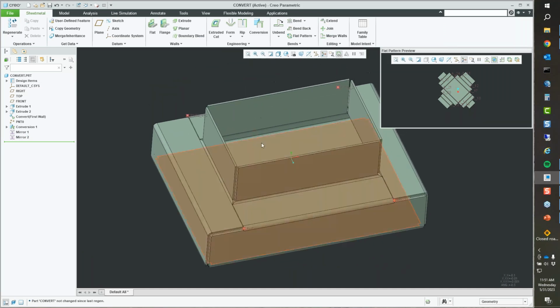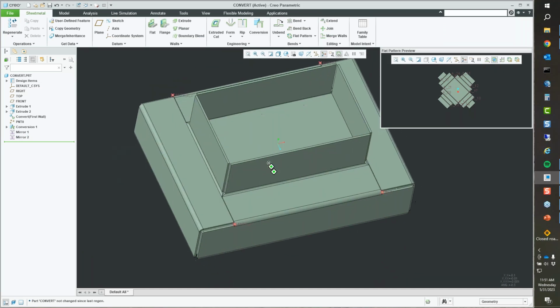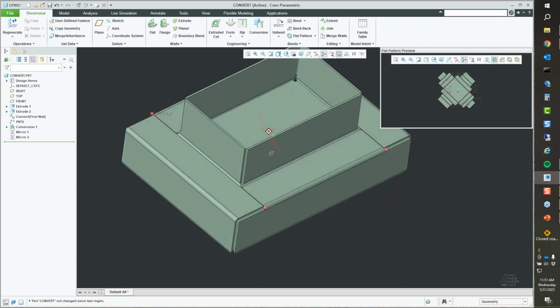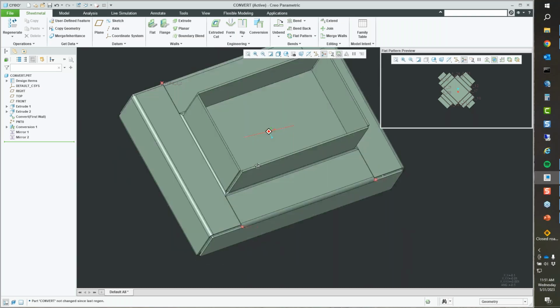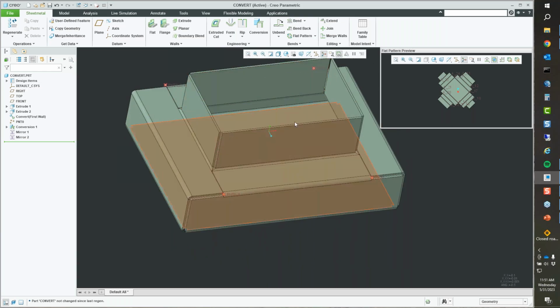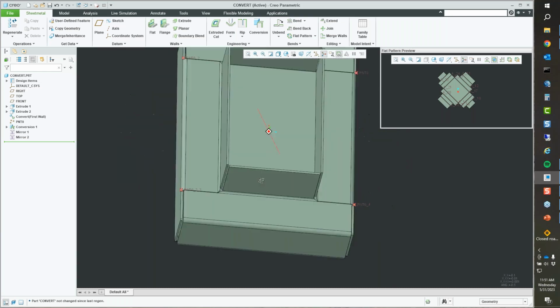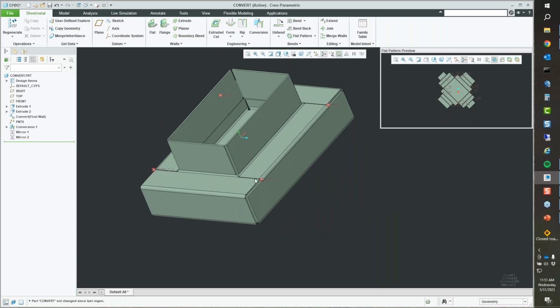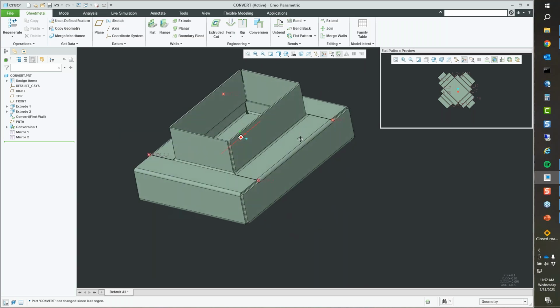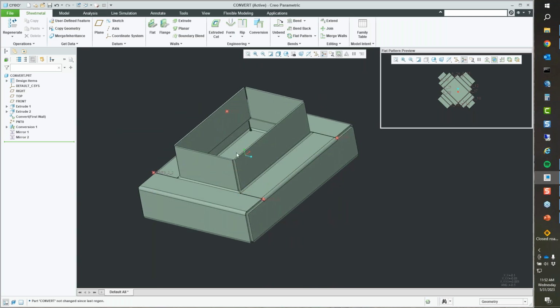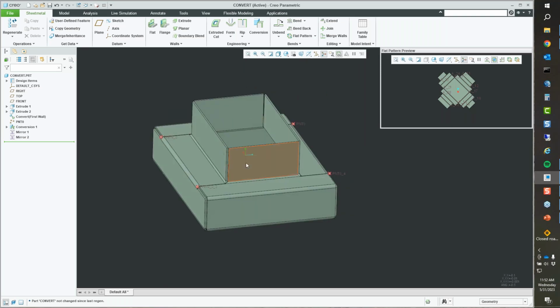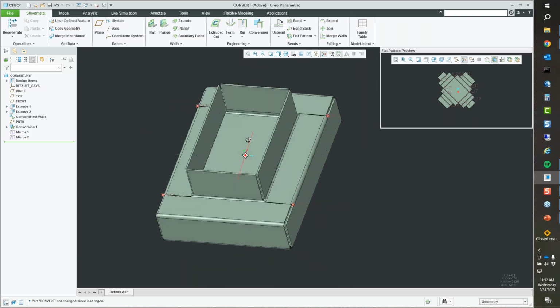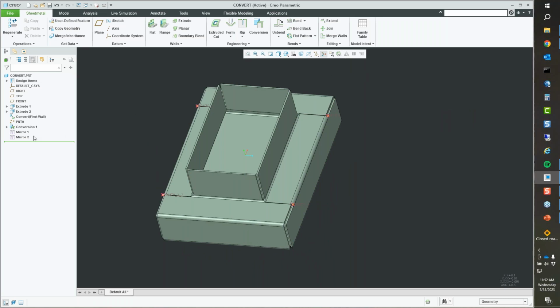Problem is, for me, for not doing that is because probably I don't have a die that's going to fit down inside of that and get me that gooseneck because of the small cut here. That'd be a pain to do. So when I've built boxes in the past, in the real world, what we've done is made wraps and then put the two sides in and either spot weld or weld. But that's a pretty common kind of setup. So I'm actually going to do a box the way I kind of like to do it in a second here. But I also wanted to show you a couple different things. So let me delete this.